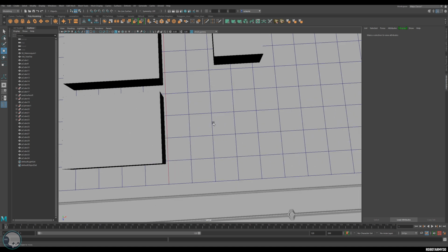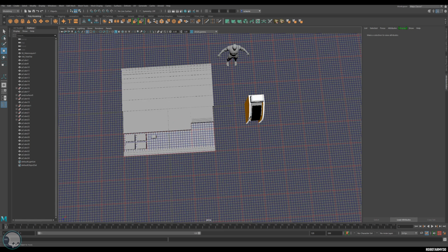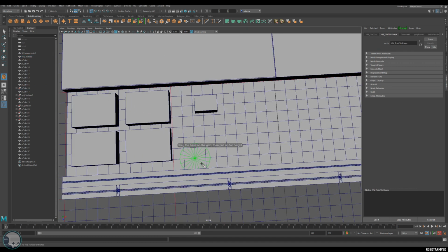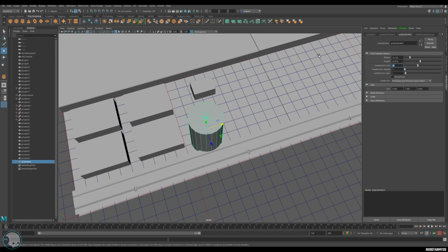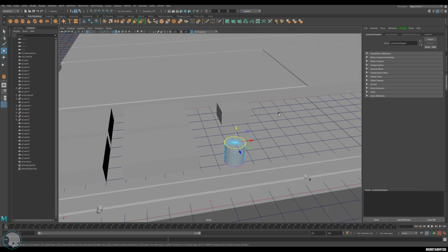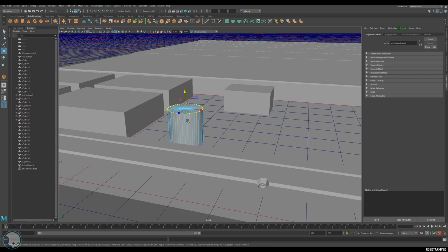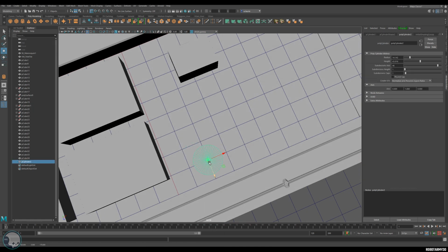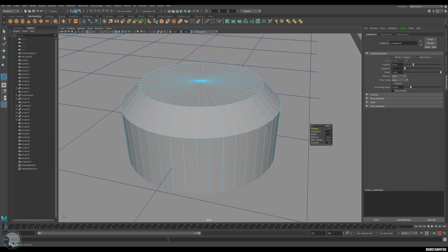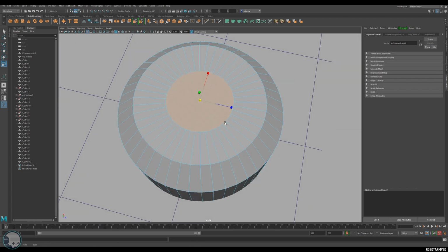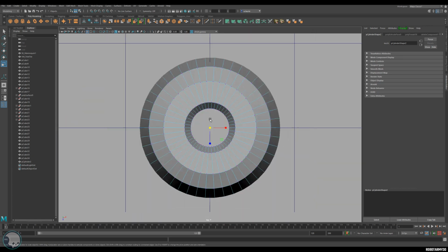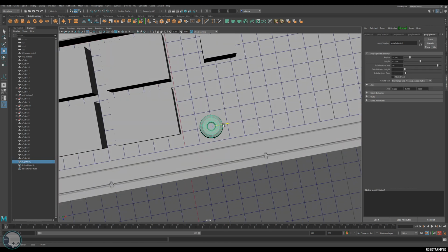And then I'm going to make a rivet as well, and a little slot for the front of this. So I just need a little cylinder. This can be pretty big, to hold the detail, but it still is pretty small on the overall size of the map. It doesn't need to be actual size on the rivets on these. You can make it a little bit bigger, because even when you get close up, one of your panels might become blurry. Having the rivets still quite sharp will actually help aid it looking like a higher resolution texture than it actually is. So make these smaller details just a bit bigger, so that you can have a little bit more detail on them.